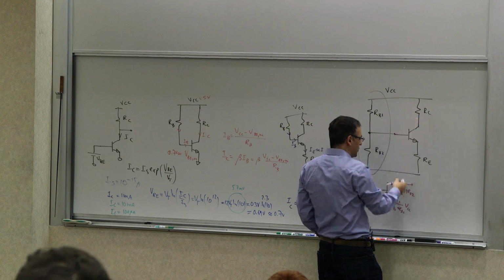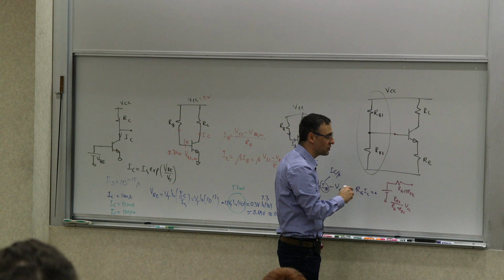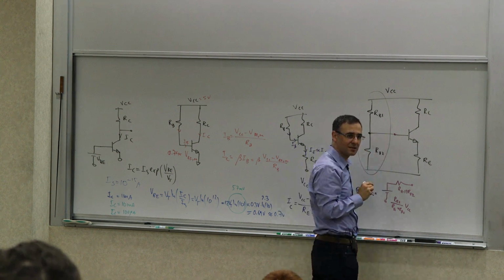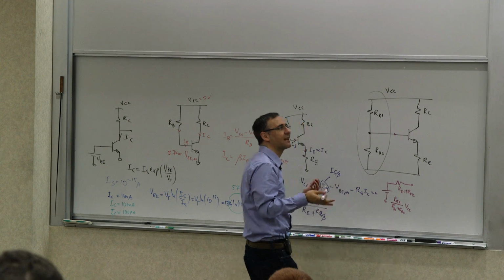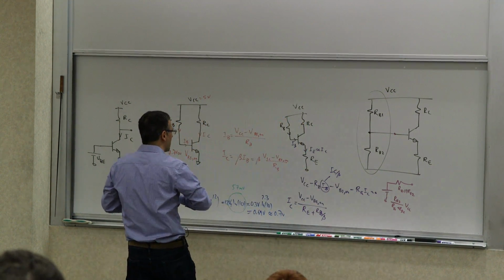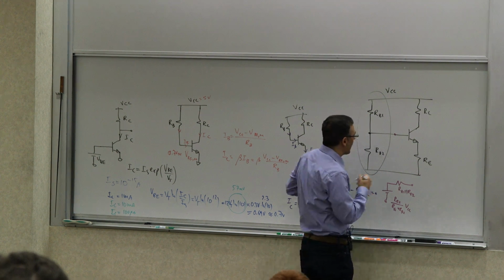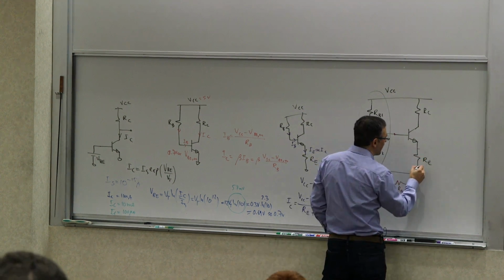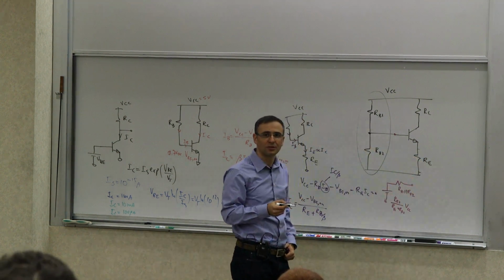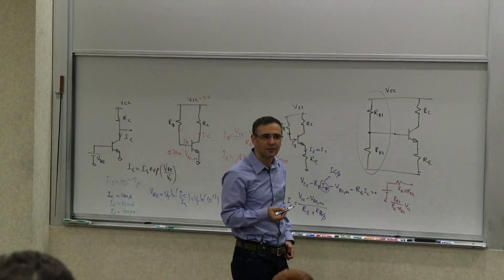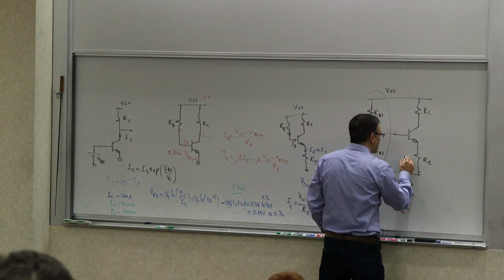Now you can use this to have two degrees of freedom to play with, setting this voltage as well as controlling this resistance. And by doing so, in conjunction with the RE, you can establish a relatively stable bias. So let's pick some numbers, right? Let's say we want to generate 1 milliamp. For 1 milliamp, let's say we want to drop about a volt here. So what should this resistor be for this to be 1 volt with 1 milliamp? 1 kilo ohm, right? So make this 1 kilo ohm.